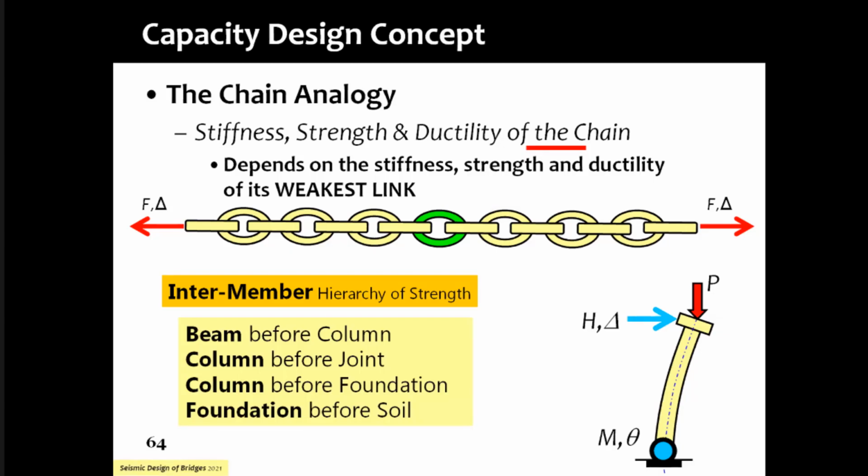There is a concept that the fellow who's transferring forces from one member to another member, that person has to be very, very strong and cannot see any damage. Otherwise, the flow of forces will not be sincere, will not be honest, and will not be accurate. And that is why bearings will still have to be rated for a higher load capacity than the substructure.